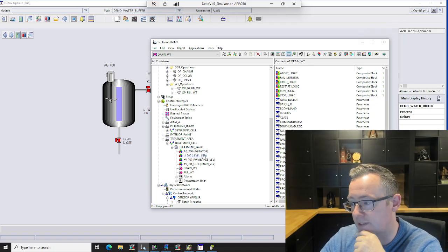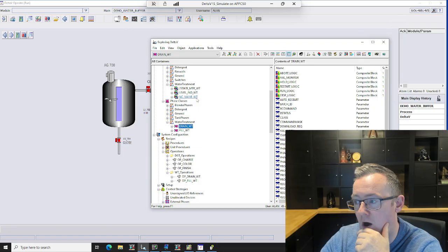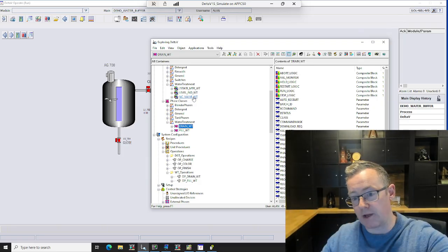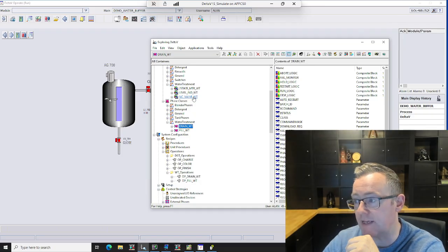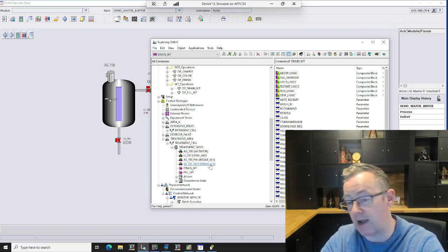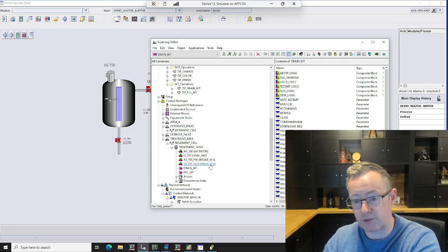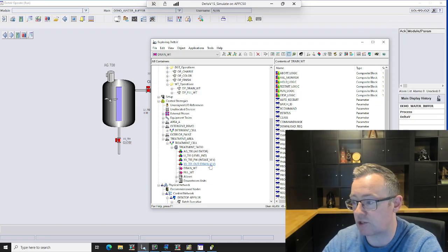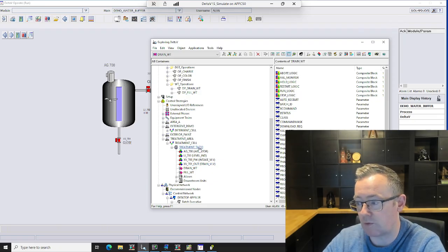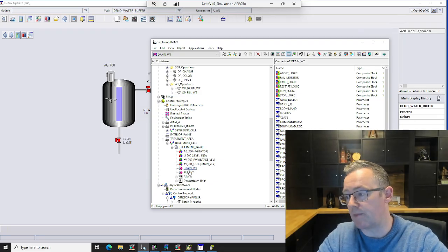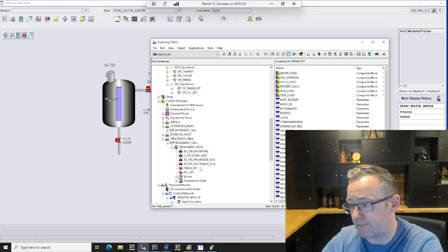These two XV valves are copies of this valve here, for example, but the rules apply to these instances down here as they're defined. All of the rules and settings in the background apply to these particular valves. And then we've created a piece of equipment, and we've associated everything with it.